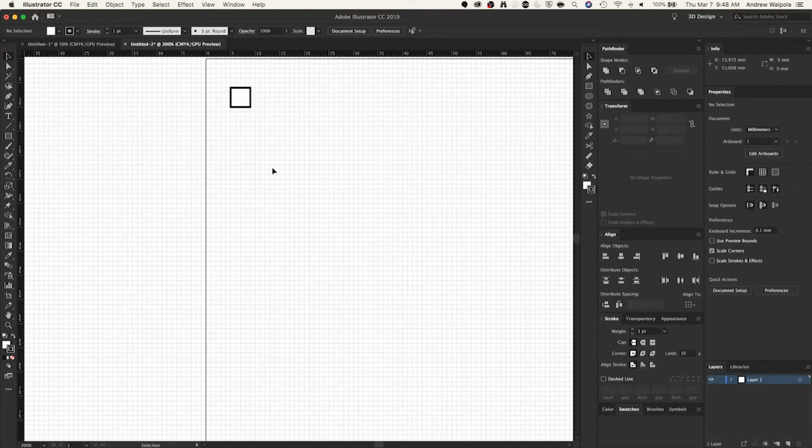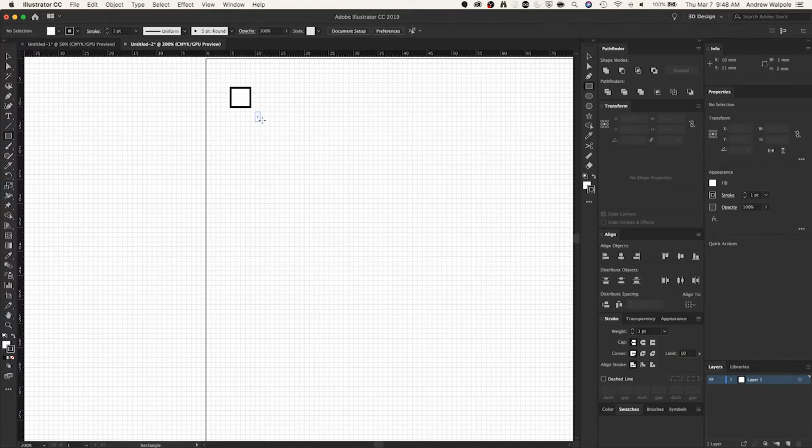And with snap to grid turned on, which we do if we go to the direct select tool. V is sort of like your home base. So pressing V, going to your direct select tool, clicking on the document somewhere, making sure nothing is highlighted, you're going to get your Properties panel to come back and look like this. So turning on snap to grid here, if I were to now press M and draw a box, you can see I can only draw in 1 millimeter increments. And so this is really nice for that precision piece, because if I don't have this turned on, I'm drawing in hundreds of millimeters as I'm dragging this out, and it's not going to be very precise.